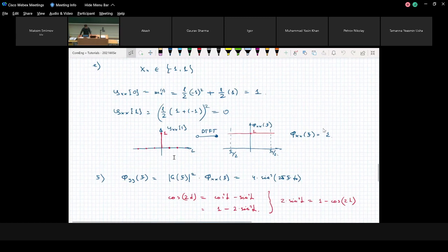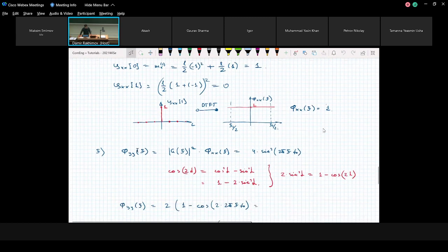And then in order to find it, we go to the frequency domain. We calculate the power spectral density at the output by using the property that we need to calculate the product between the input power spectral density and the squared value of the transfer function.